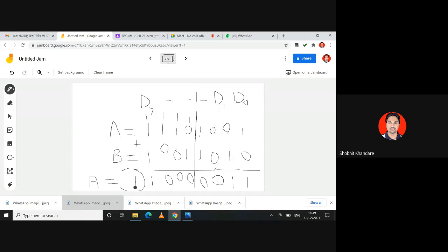And whenever there is an overflow, how is this reflected in the PSW? This is reflected in the overflow flag. So you have the overflow flag given by OV. In such conditions, whenever the carry is generated, your overflow flag becomes 1.